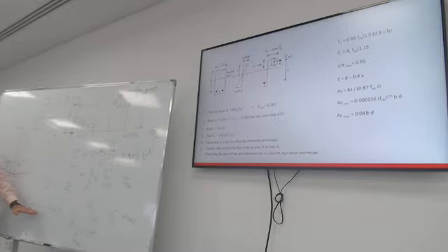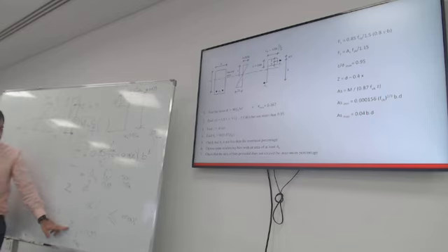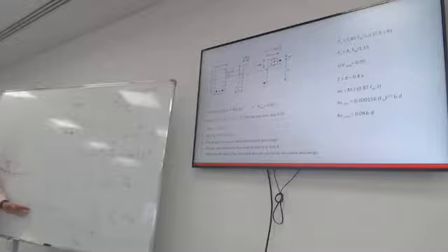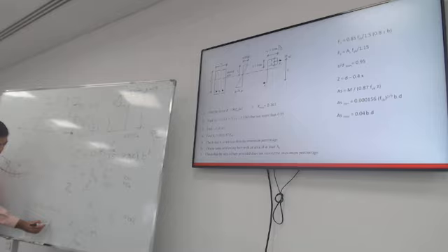So the code will limit it to something around 0.45, but it comes from this relationship. Once you know Z over D maximum, you can figure out what X over D max is. Does that make sense? Z over D equals 1 minus 0.4 X over D. So from Z maximum, you can figure out the X over D max.